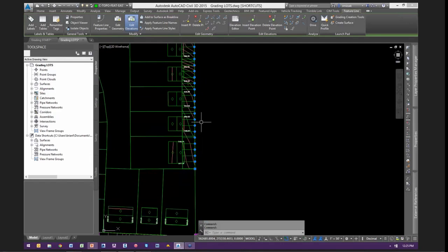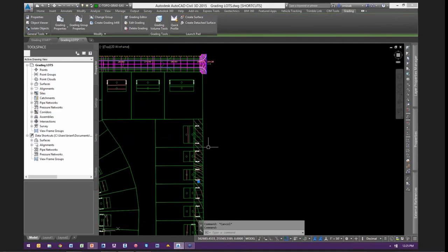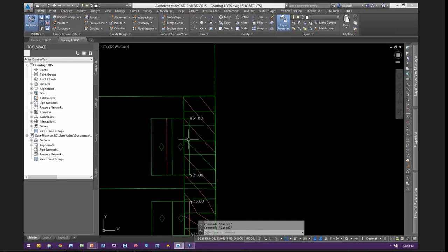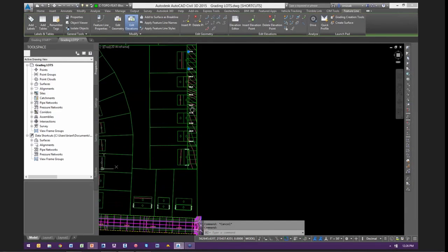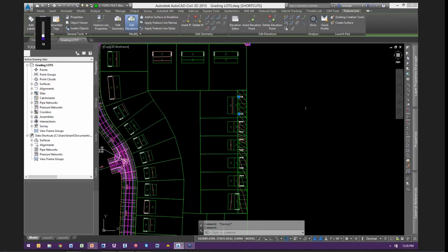So I can drop a feature line there, and then from right-of-way, again, we want to assign pad elevations, some kind of typical or constant slope up from right-of-way. So what I've done is I've taken that feature line and attached a very simple grading object to it. If I go through the editing of this grading option, you can see it's at a 5% grade, coming up at a 5%. And the distance we went was out there. So now I have a surface out there, and I can grab all these feature lines and pull elevations from a surface that's based on elevations at existing right-of-way.